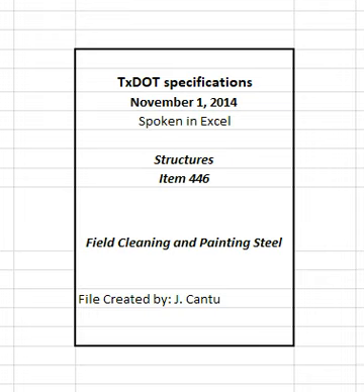4.7.5 Handling and Shipping. Pad the blocks, chains, slings, braces, clamps, etc., used for handling, moving, storing, and shipping painted members so the paint will not be damaged.